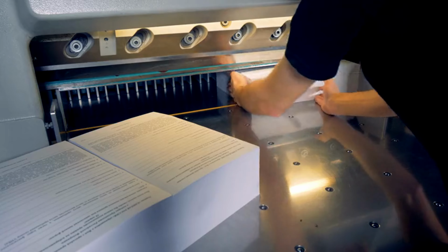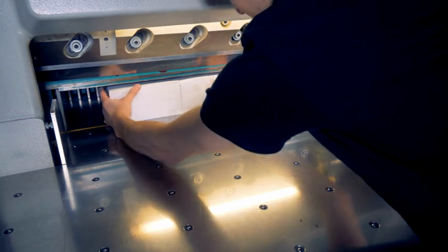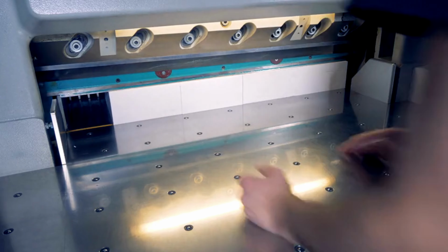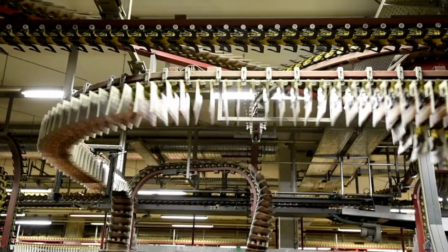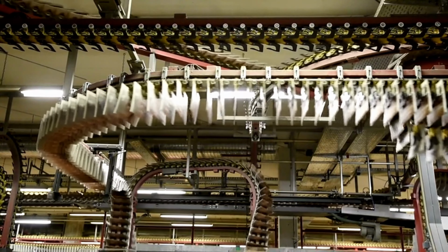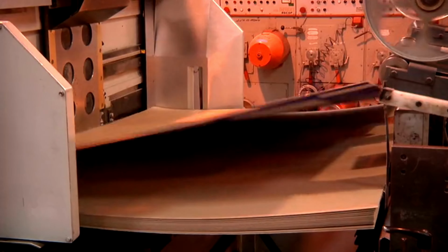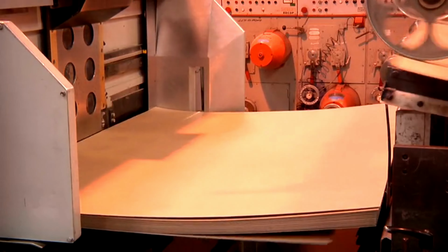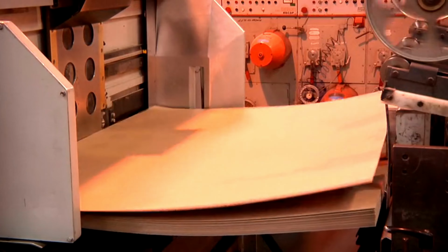3. Automated paper sheet formation. Paper sheet formation has evolved to use real-time sensors and AI-driven monitoring. A. Modern Fourdrinier and twin-wire machines. The pulp suspension is computer-controlled to ensure even fiber distribution. Laser-guided thickness sensors ensure uniformity. Multiply formation mills can create layered paper sheets for specialized uses, for example, multi-layer cardboard and coated papers.